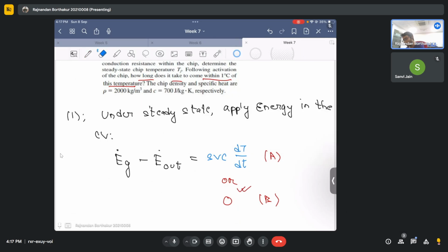Okay, so try to understand. Although this is an initial transience problem, in the first part they are telling us not to worry about the initial transient state. We are just asking you that after that initial transient state takes place, once you turn on your laptop and your chip temperature rises from a particular equilibrium temperature to a steady state temperature, what is the final steady state temperature? Then we can do this analysis in steady state because we don't need to worry about the initial transients.